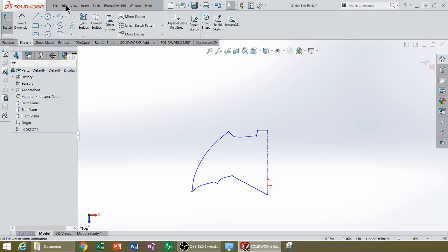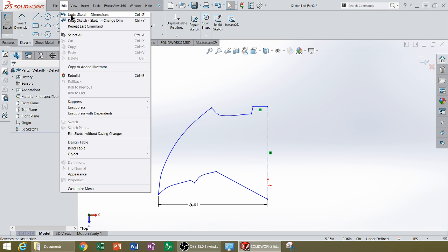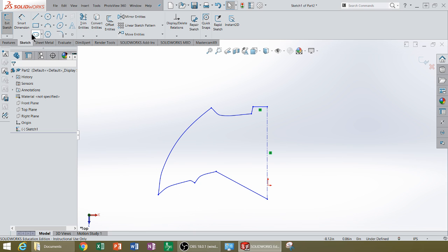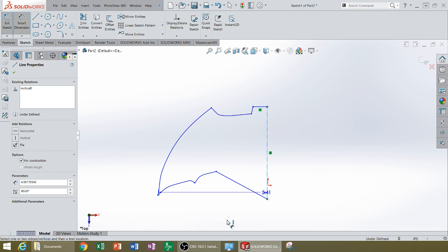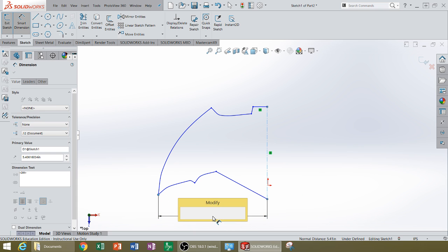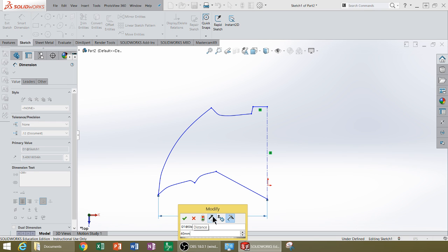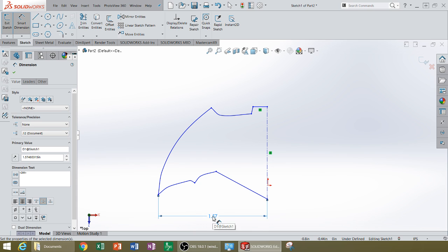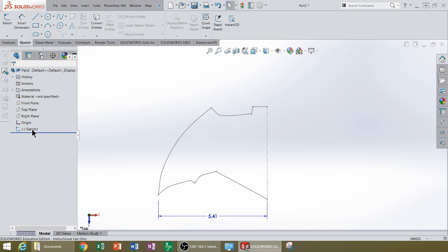Let me undo my sketch dimension here twice and redo that. Set my first scale here. There we go. So now I'm 40mm, and while I'm at that, I'm going to change to millimeters, grams, and seconds in my sketch, and you'll see my sketch is woefully underdefined.